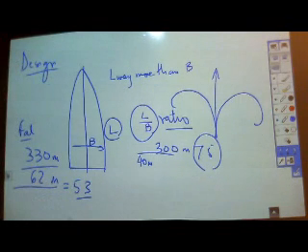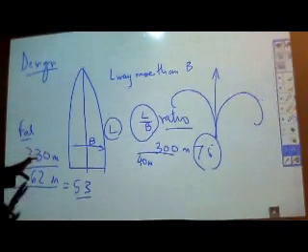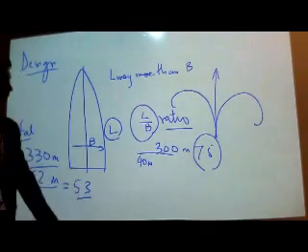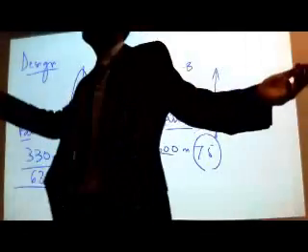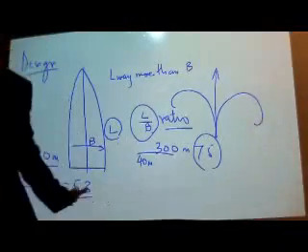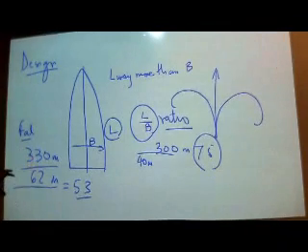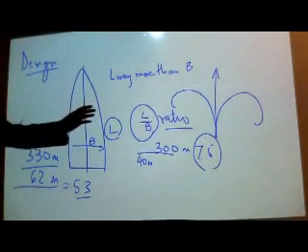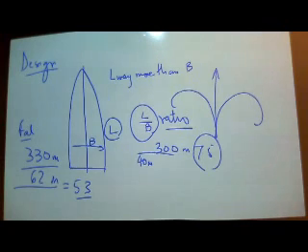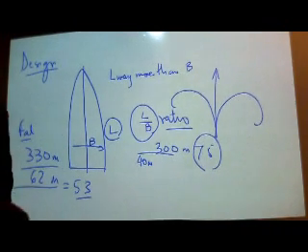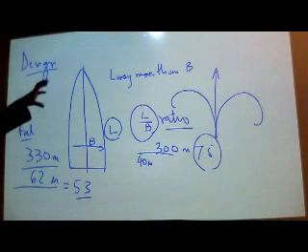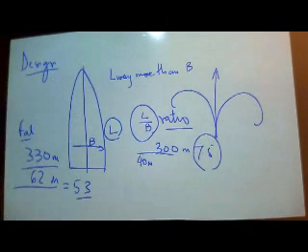And also for maneuvering, the other important thing is the V shape or U shape. We will look into that. Now this is the length versus breadth ratio here, and this is the length versus breadth ratio of a container. We are looking at two extremities first. It is always easier to look at things from the point of view of extremities. These are two extremes. A ship which is block shaped, moving bulk as well. That ship is not block shaped, more streamlined. And then of course there will always be ships somewhere in the middle range.